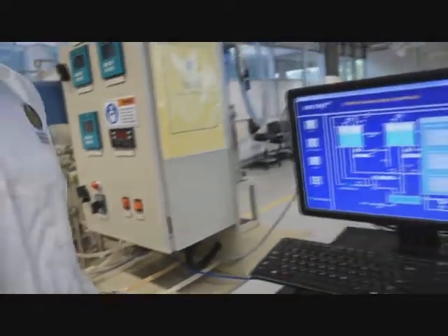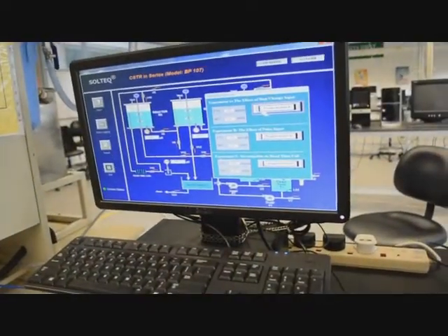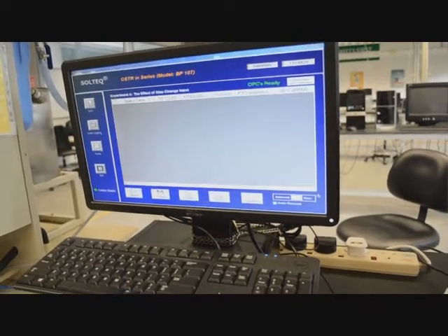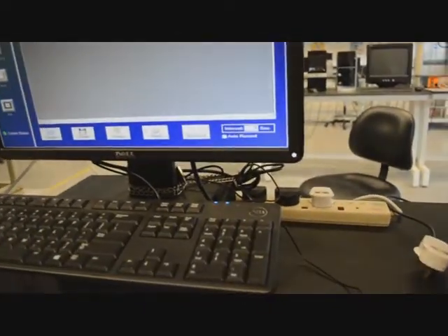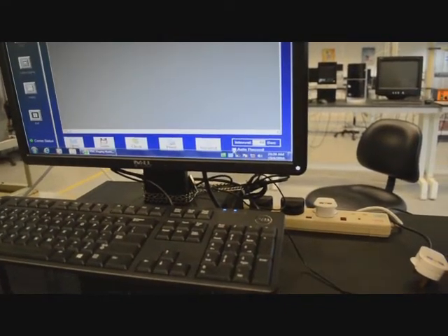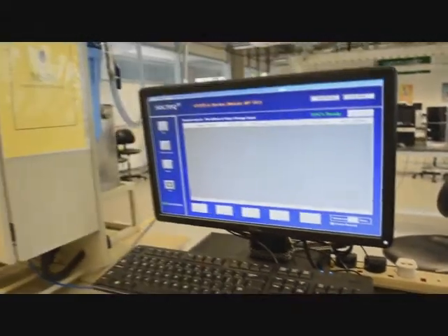We go back to the software. We have to record the conductivity values. Click on experiment A, and we have to set a suitable interval, which is 60 seconds, and click on auto record as we simultaneously switch on pump P2.